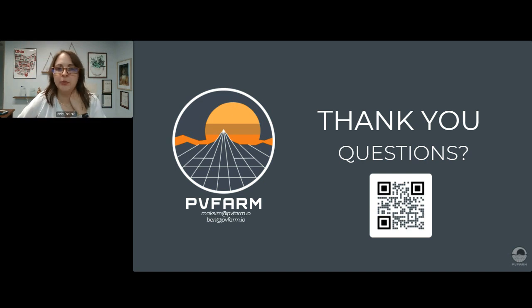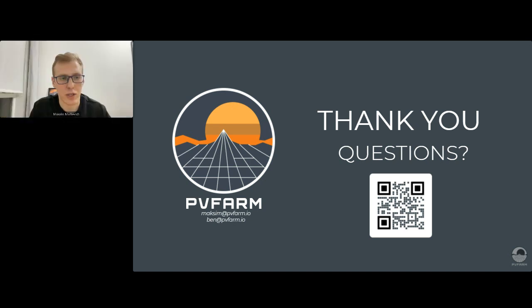Can you input LiDAR data? Can you import CAD files? What can you import into the program? Yeah, so I would say that terrain, especially terrain, our customers bring it from Civil 3D. So we build a specific plugin for Civil 3D. So basically, if you can upload and open your terrain in Civil 3D, you can import it to PVFARM. We also support LandXML, DEM, and GeoTIFF. That's pretty much it.